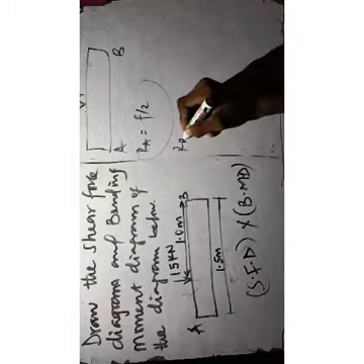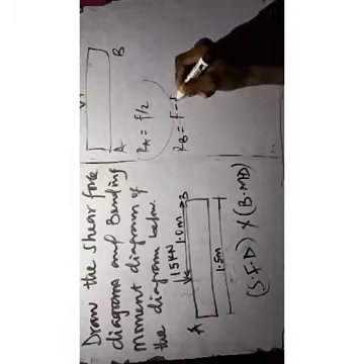Because for any simply supported beam with a force acting at the center, without any other external force aside from that, the answer is F over 2. And if you remember, your RB was also F minus F over 2, which is your RA, the F over 2 there. So that's very simple.